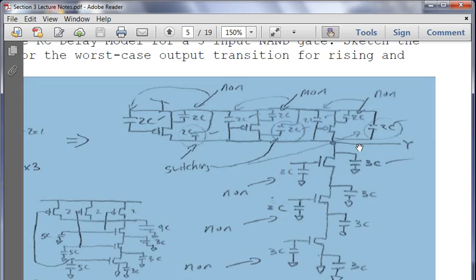And so what's going to happen is we're going to have an example where we have a 3-input NAND gate, which is going to drive the fan out, known as some n number of 3-input NAND gates, right? So then what's the capacitance there? We're going to learn that it's 9 plus 5H C, because H is the number of circuits it's driving.